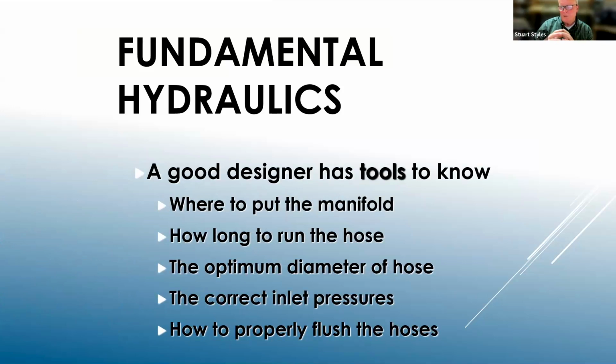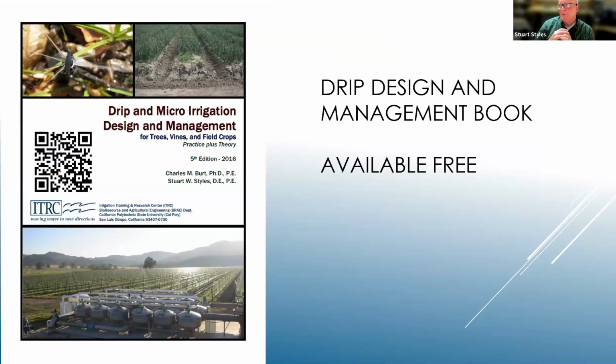How long can we run hoses? Doing friction calculations: what diameter hose do we need? What are the correct inlet pressures to make everything have a good uniformity? And then can we flush those hoses easily out in the field? The basic hydraulics aren't real complicated here. It's a matter of knowing how to put the pieces together and use the right tools that are available. Our design book has been used for decades now.